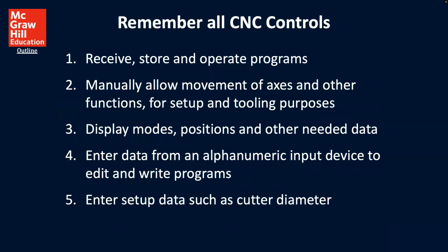So remember all CNC controls: 1, receive, store, and operate programs. 2, manually allow movement of axes and other functions for setup and tooling purposes. 3, display modes, positions, and other needed data. 4, enter data from an alphanumeric input device to edit and write programs. And 5, enter setup data such as cutter diameter.